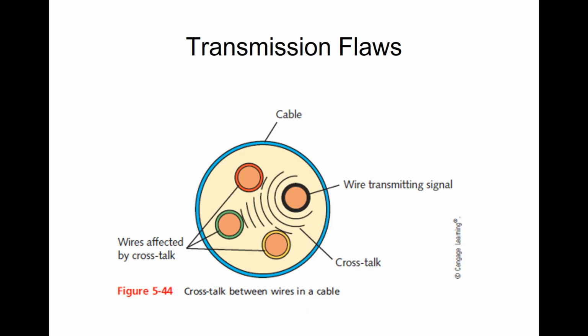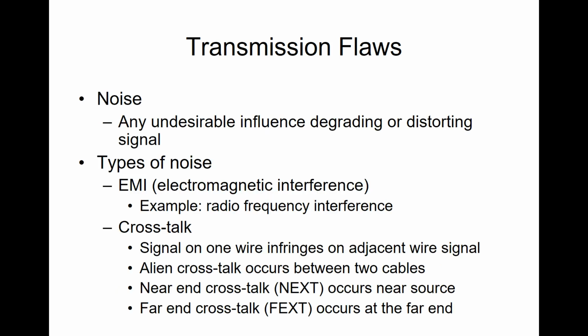But what it really does is those cables are sitting next to each other, and we have this crosstalk from one to the other, and this cable sending a signal, and this one picks it up. So that's that idea of crosstalk. So we want to minimize that. And one of the things we do to minimize that is we don't run cables next to electrical cables, for example. So we want to put our data cables at right angles to power cables as much as possible.